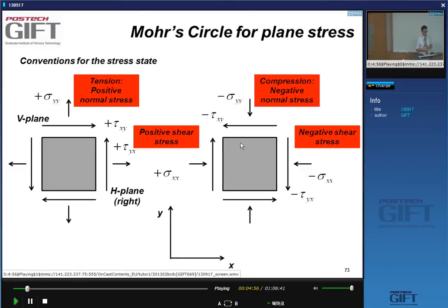We've learned how to use it, but very quickly we've really lost the ability to use it because it's rather complicated in terms of orientations. If you want to know the stresses, you have to rotate in a direction different from the direction that's on your graph, and then sometimes you have to divide the angle by 2, and so we tend to forget how it works, and we don't use Mohr circle.